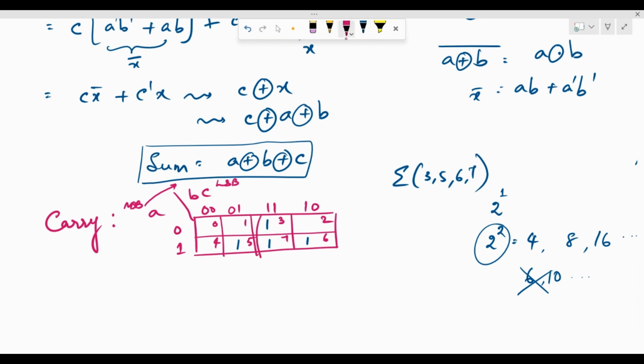So this is the first group. Now let me tell you how to write the expression for this. On grouping, first analyze the rows and see whether the particular input represented in the row is changing or not. So here, both the ones are spread across both the rows, and A is changing from 0 to 1 over here, right?